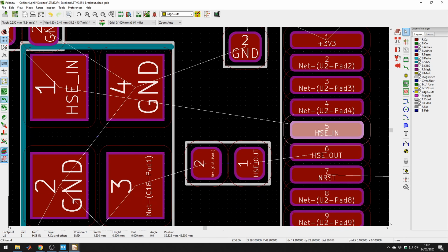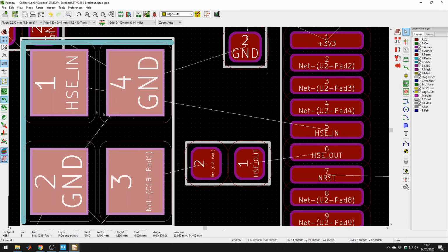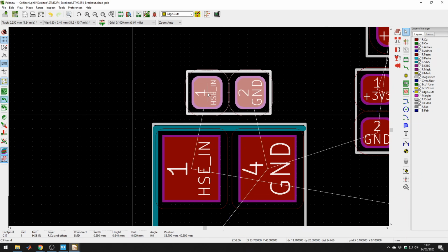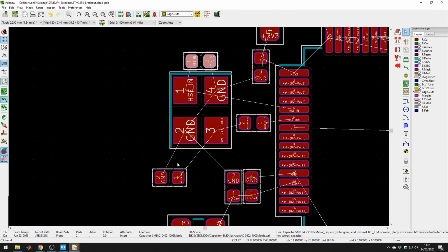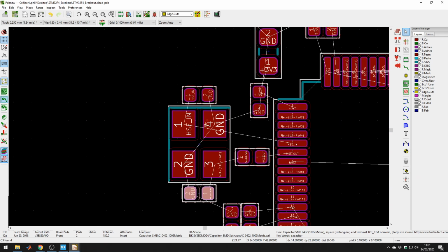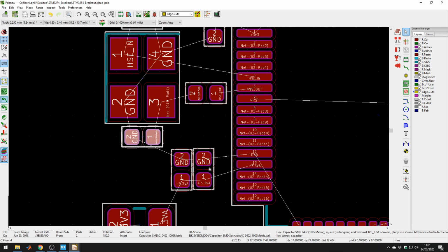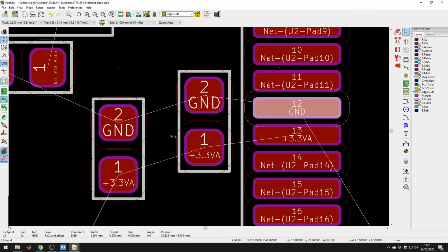Okay, this is going to come out like this, so maybe move it up a bit. There we go, so I have a nice straight connection here. Let's put this central and fairly close. These are the load capacitors. I'm making sure everything's aligned nicely and symmetrical, and this looks pretty good. Let's get them very close and central. If I press M, I get these guidelines of where the center of the component is, so I can take out the traces nice and symmetrically.